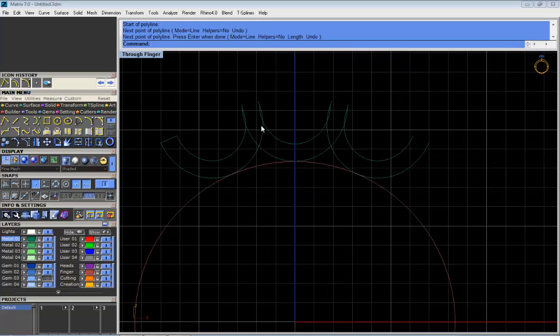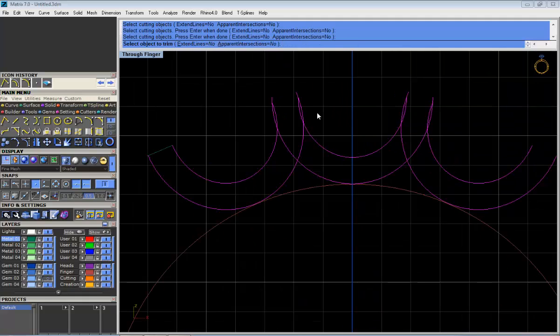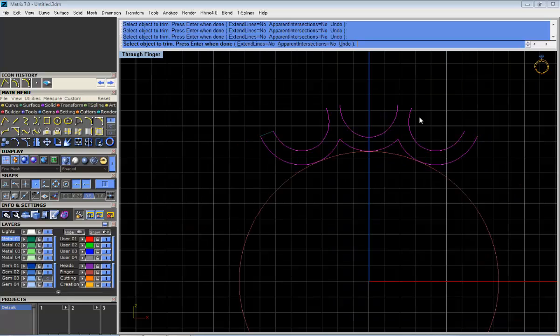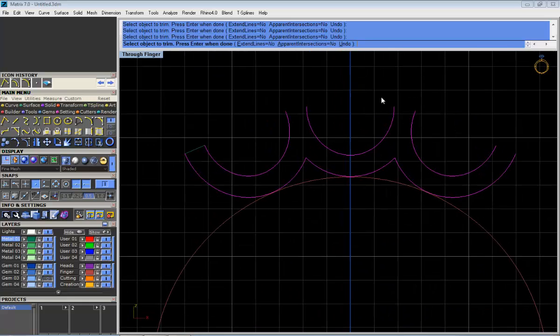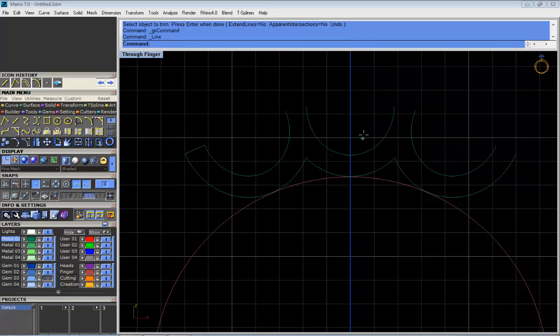and in this case I better click on trim before, and I'm gonna select all these curves, well, all these actually, enter, and I'm going to remove this one, this one, this one, this one, these two on the top also. Okay, just to make sure that I don't have any extra line. Okay, I should be having something like this. Let me check. Yeah, that's right. And I'm gonna close all these lines, always from end to end. Okay.